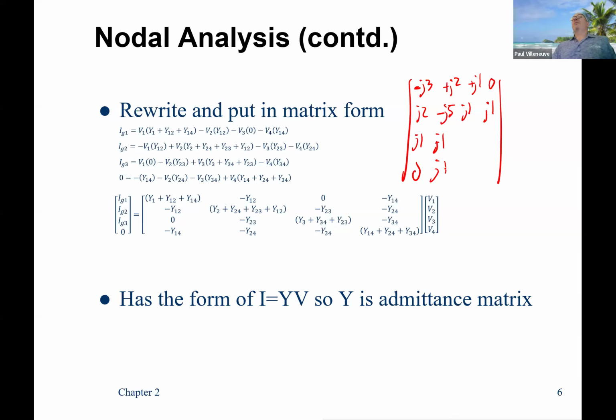And that's because when you invert, if it's an impedance that's reactive, when you invert it, it becomes a negative J, right? Because we talked about a 3 ohm reactor or inductor is J3. And then when you invert that, that becomes 1 over J3, which is negative J 1/3. When you take the negative of that, you end up with positive numbers.